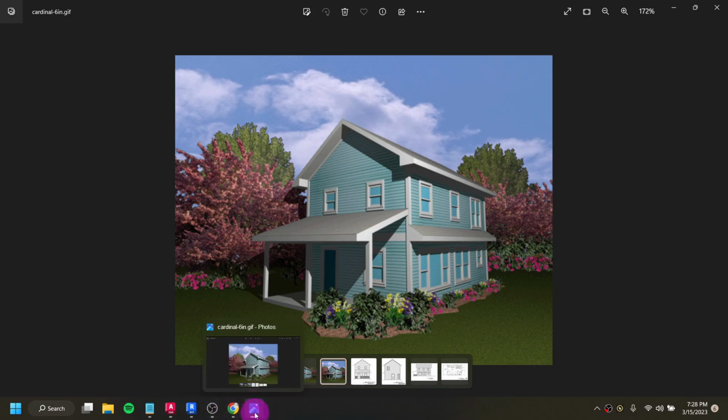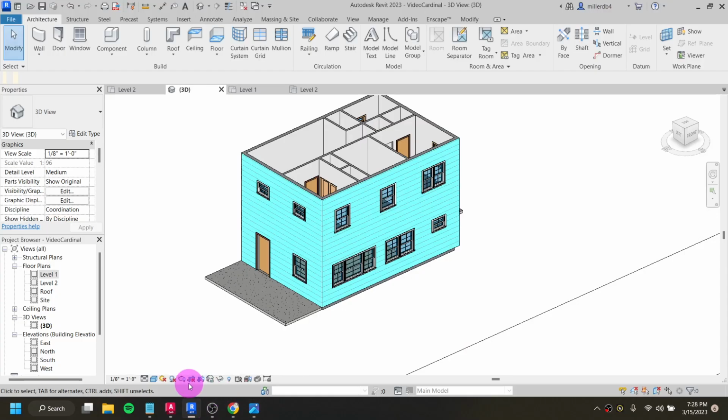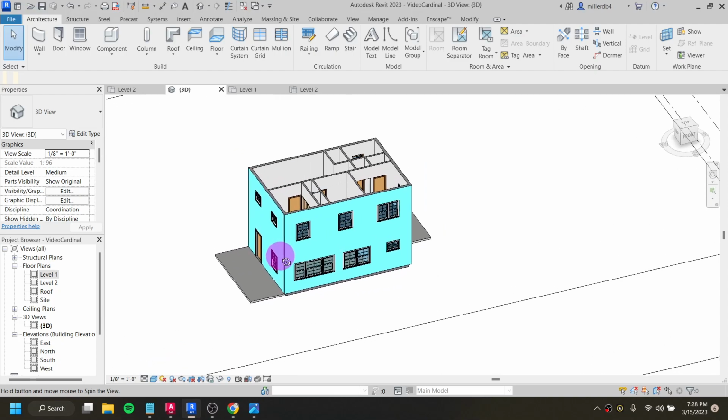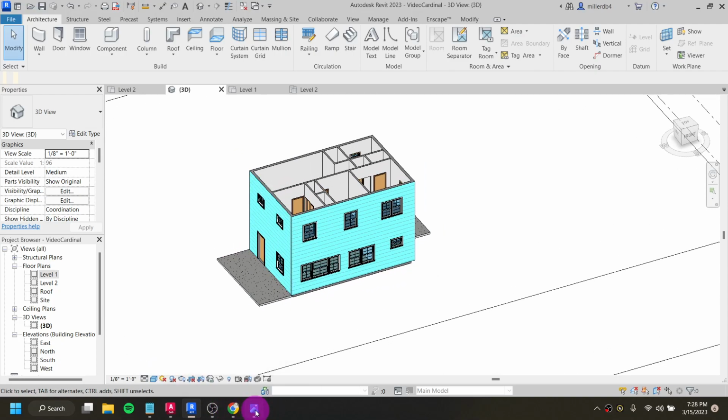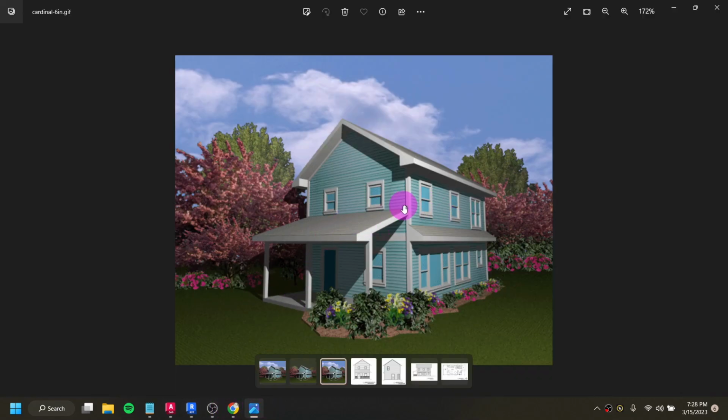Then the next thing we're going to do, let me get back into Revit, is put in our roofs. So we actually have 3 different roof systems that we're going to have to create. We have our just plain gable here. It's got a little bit of an overhang, and we also look at the AutoCAD drawing just to make sure we have the slope correct.